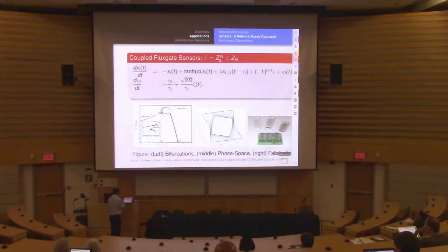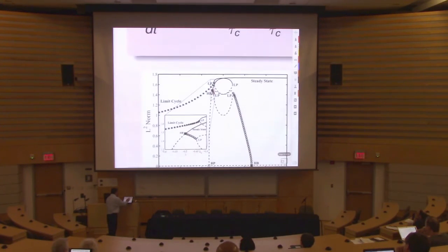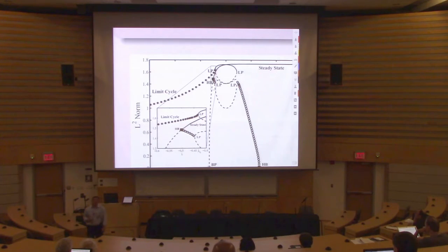Let me back up a little bit. When we added delay into the system, when we power up the sensor, most of the times it was almost oscillating. So when we did the analysis, that's where I got the help from John Mahaffey. We did the analysis, including delay, and we found an optimal value of the delay. From the bifurcation diagram, added delay into the system pushes the location of this half bifurcation towards the right, and the onset of the heteroclinic cycle to the opposite side.